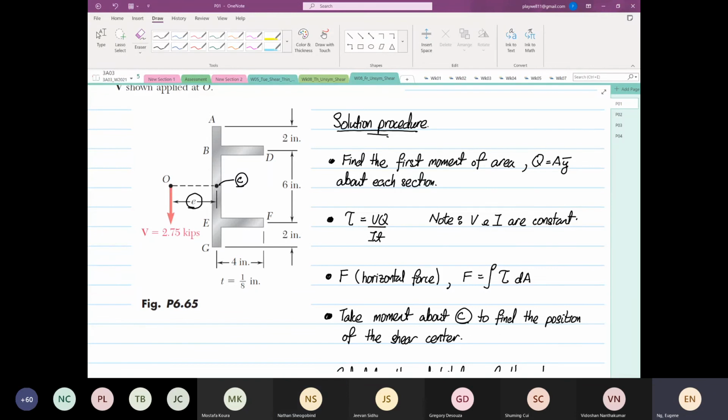If it's a thick wall, do you have twisting? Assuming that the structure is rigid enough, for a thick wall, based on the force that we apply, there will be zero twisting. So you don't need to consider it. This unsymmetrical shear is basically when you have a twist.